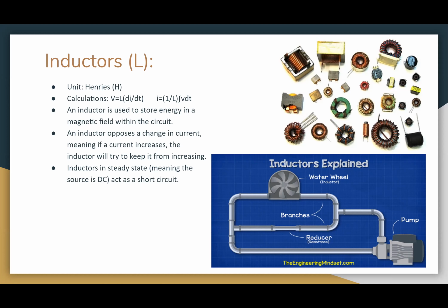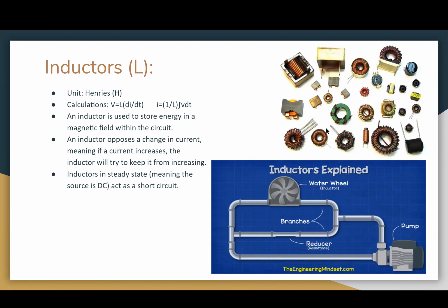A good way of remembering this, the big takeaways for capacitors and inductors: they both store energy. Capacitors store it through an electric field, and inductors store it through a magnetic field. And also, when connected to DC current, they behave in 2 different ways. With the capacitor, it acts as an open terminal. The best way to remember that is with the capacitor having 2 sheets, and in that open area, that's where the electric field is. So just remember that if a DC source is connected, it's going to act as an open terminal.